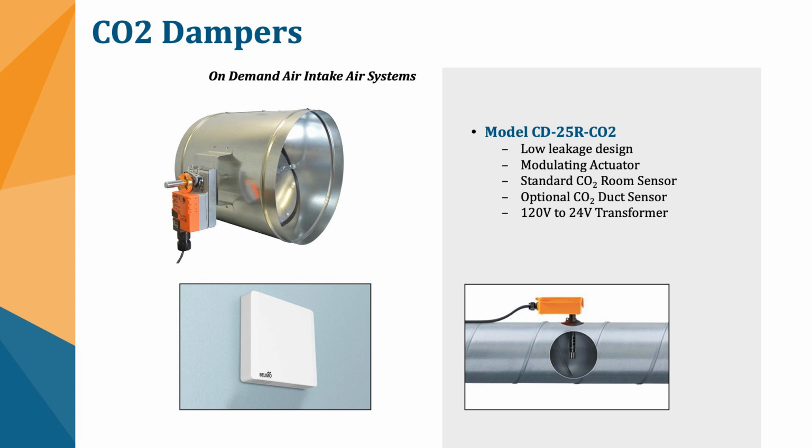And that's actually one of the questions I get: why wouldn't we have these sensors duct mounted? Typically you're not going to want to measure your CO2 levels anywhere but, say, inside the room, so a wall sensor, or on your return air duct, which a lot of times these occupancies don't have a dedicated return air duct. A lot of times they're either going through a grill and a mechanical closet door, or a grill and a wall into a mechanical closet that's a little more free flowing, and it's recirculated that way. And you may be then opening a separate duct to increase that fresh air from the outside as your CO2 levels or even your humidity sensor levels increase.